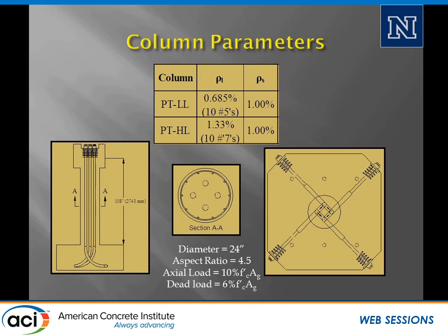And what we also did that was a little bit different than other people have done is they've tended to concentrate all the tendon force in one location in the middle, which is fine when you're dealing with a scaled column. But if you're actually looking at a real full-size prototype, you're not going to be able to put all the post-tensioning in the middle. And so we looked at the case of spreading out that post-tensioning out here in the boundary. And of course, that's going to alter the behavior of that post-tensioning.